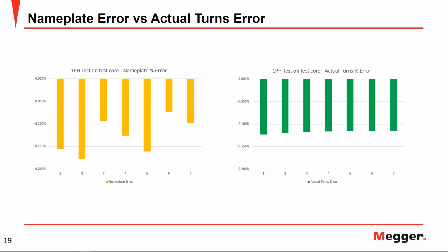The excitation test is a voltage dependent test. If I run the test at 500 volts, 1000 volts, and 5000 volts, I will get different excitation current measurements. Now the question is asking about the relation between rated voltage and excitation voltage.